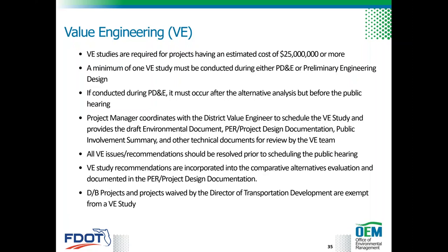Value engineering. So all projects except design-build projects with an estimated cost of $25 million or more are required to undergo at least one value engineering study, or VE, prior to final design. A value engineering study can be conducted during PD&E or during preliminary engineering design, or PER.